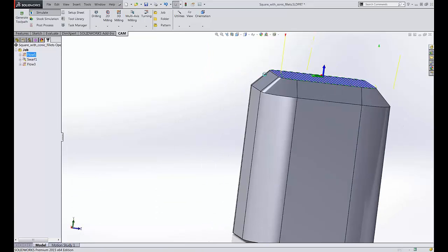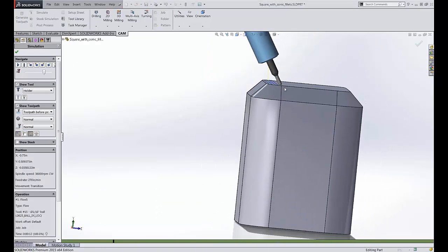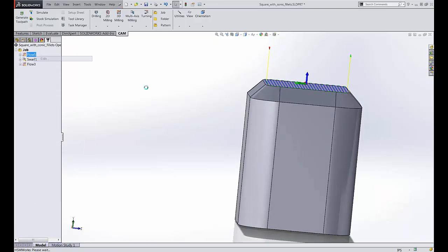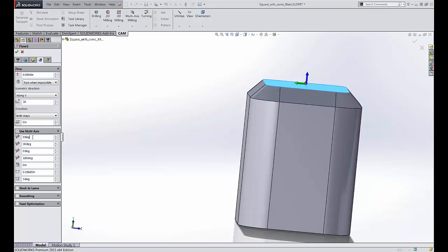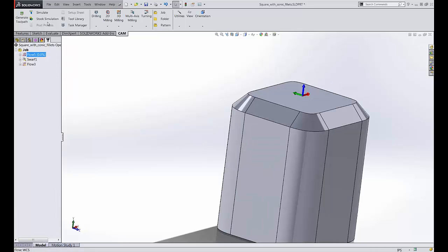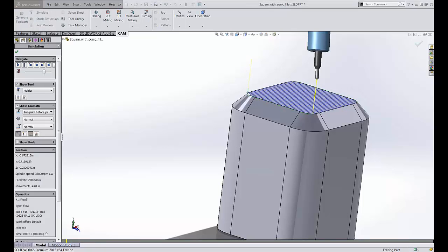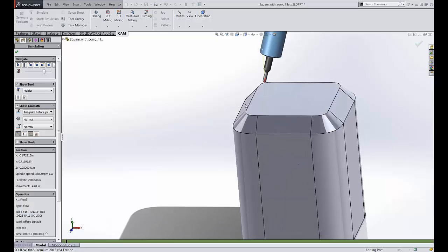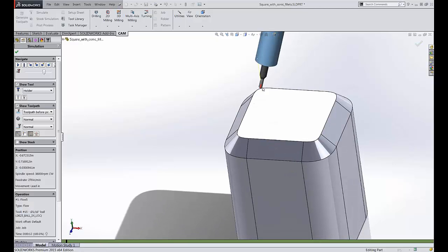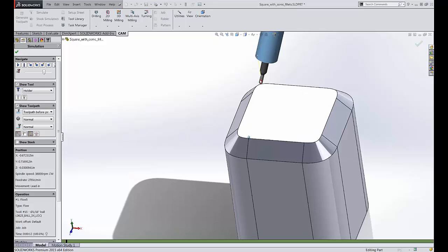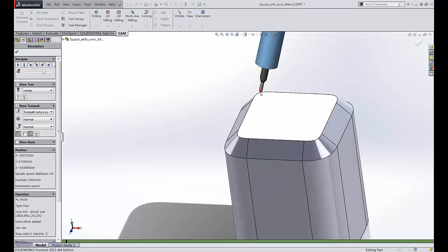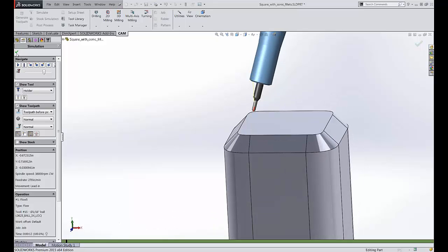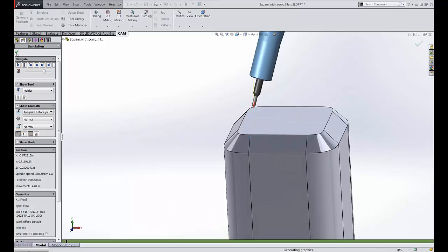And you have tilt in the other direction. And obviously you can use a combination of the two. We can say 15 degrees, 15 degrees, and it will be tilted forward and sideways. This is a great option for when you're just trying to maintain that constant tilt angle on a surface and keep the tool off of the tip. That's effectively what those controls are largely used for.